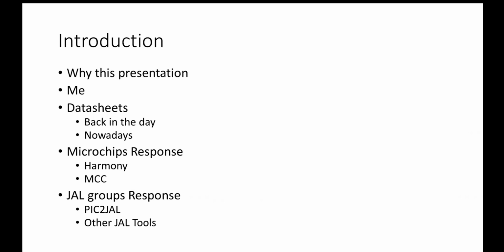And what happens is they've written those pieces of software in a universal language whereby the same register is called the same thing irrespective of the chip. Let's say I write a CAN bus bootloader for one chip and I write it using Harmony, then I can pick it up and drop it on another chip and it'll mostly work. I might have to do a tiny bit of tweaking, but for the most part, I'm on the air.